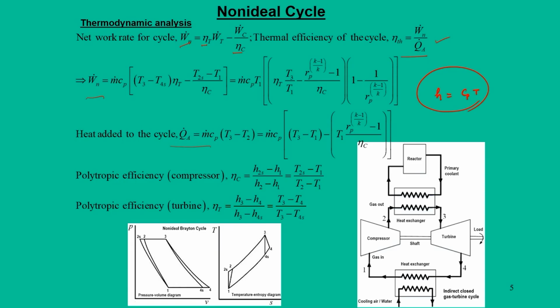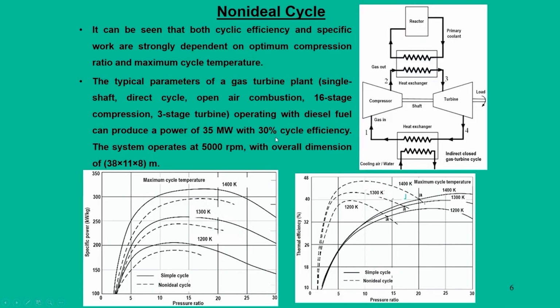Normally, when you deal with similar kinds of efficiencies for steam turbines, we used to get this value directly from the steam table. But in this gas turbine cycle, your working fluid is purely gas. So, we take the ideal gas assumption, and accordingly enthalpy is represented in terms of Cp times T. So, compressor and turbine efficiencies are introduced in terms of temperature differences.